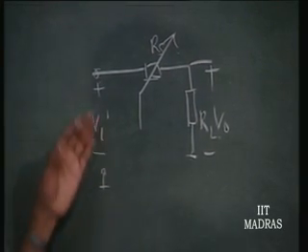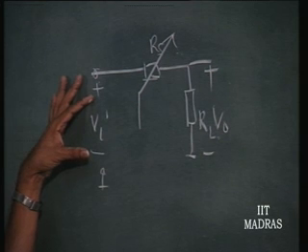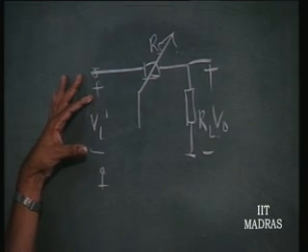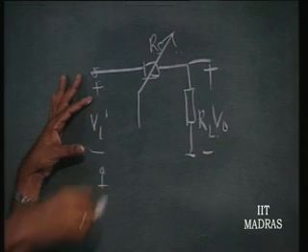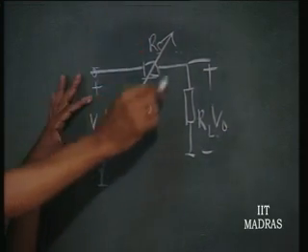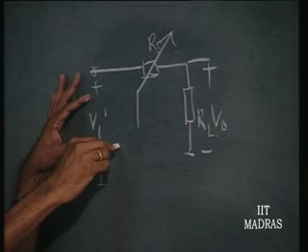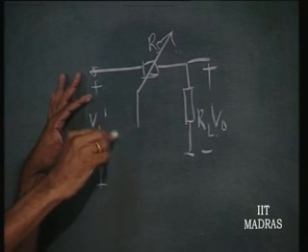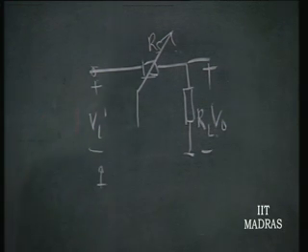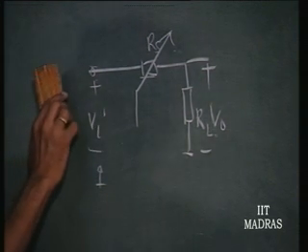Obviously, if input voltage is varying by a very large extent, then we have a serious problem of power dissipation in the IC increasing, particularly when Vi is reaching Vi max. Okay. So, this cannot be avoided in this. So, this series regulator is not an efficient scheme.